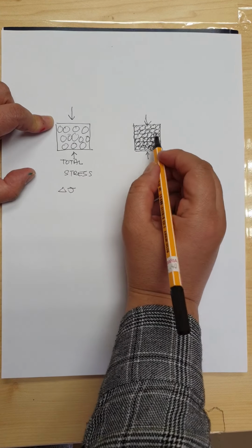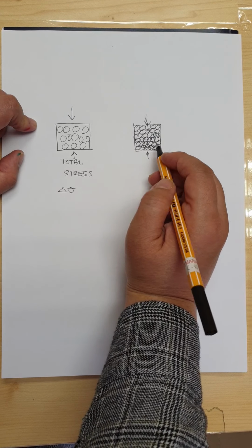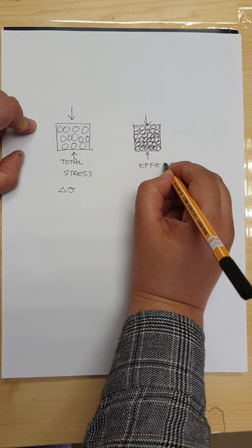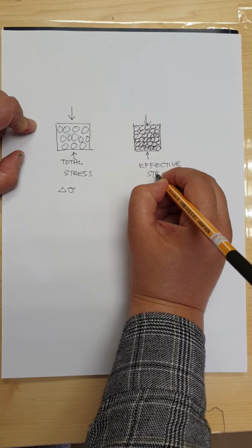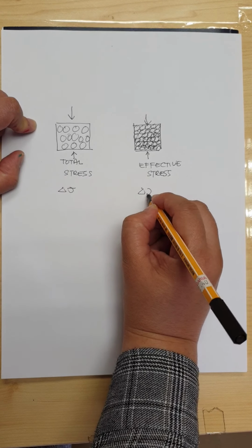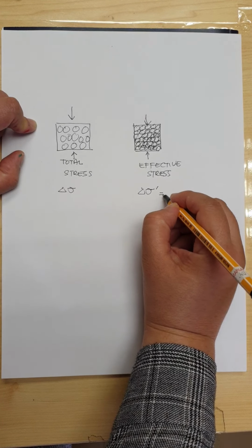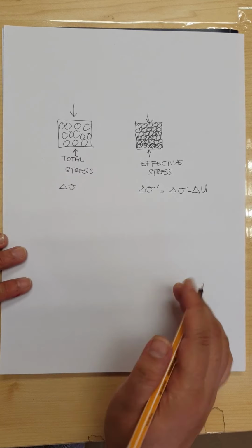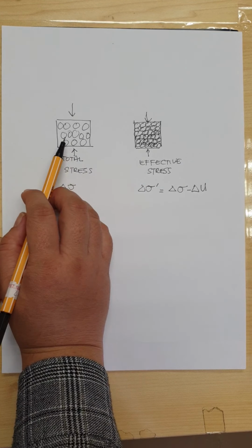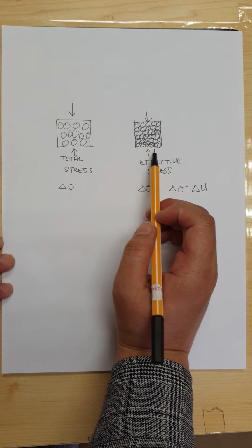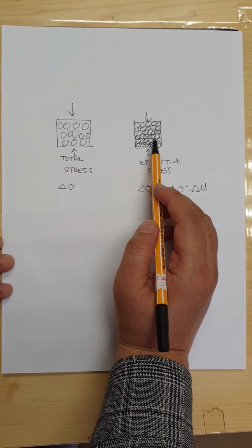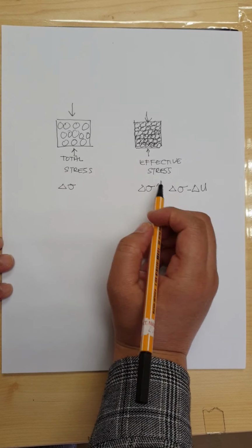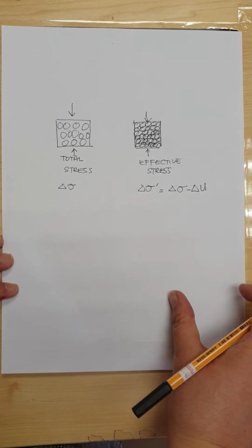If we consider everything is only soil solid, that is what we consider under the analysis of effective stress, and we will use the expression effective stress equals total stress minus pore water pressure. Meaning that for effective stress we exclude pore water pressure, and all that acts during effective stress is the soil grain only. We are not including anything from the pore water pressure.